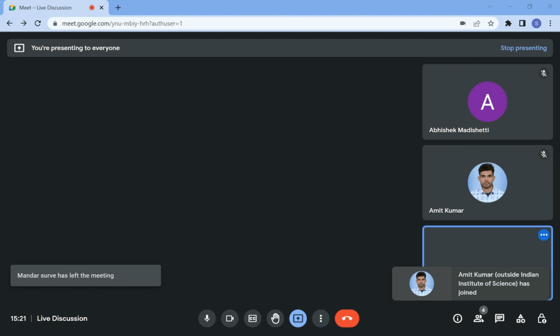So when I'm rotating it without changing the angle, I know that this point B is going to trace a line here. So to find the true angle, I know that point B should be along this, and I know the true length. So to find the true angle, I will take the true length in the compass, and I'll make an arc here. So this will be my true length, and my B point is on this line.